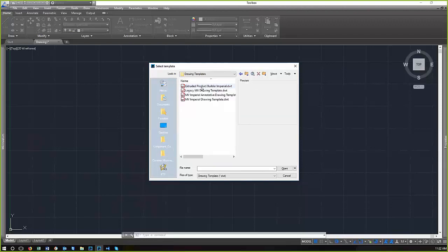So if you need to make changes to your template, every time you open a room, you get a copy of your template, and that's your current DWG. If there's something wrong with that DWG or something that you'd like to change because you change it every single time, what you do is you go into your template, make that change there, and then every time you make a new job, it's going to come up with that change already made in it.